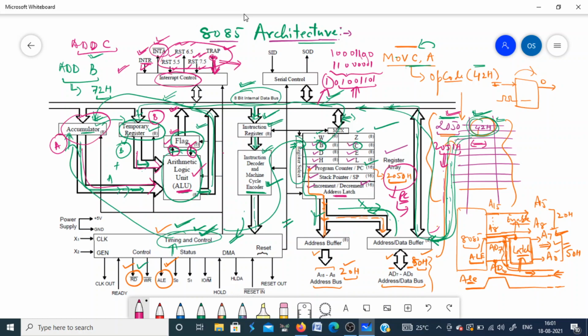If there is a processor which is used to execute any task, and suppose you have some fire sensor whose output is connected to this TRAP, it means whenever there is a fire in the building, of course that is an emergency situation. So the processor has to service that request. Whatever it is doing is not as important as that emergency situation. So such sensors you can connect to this pin, which have to be processed at top priority. Of course we will discuss these blocks in detail.